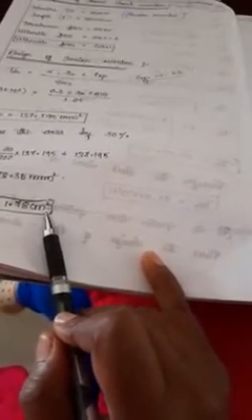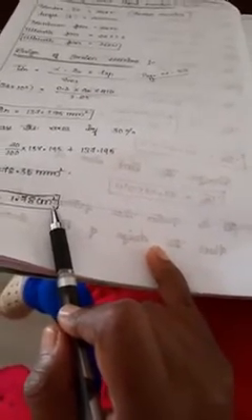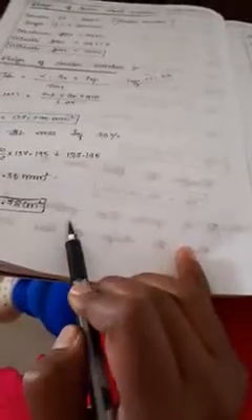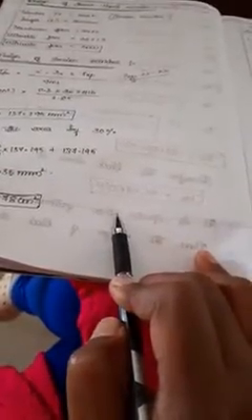For example 50 by 50 by 6, or 70 by 70 by 8, in that way you can select it. Don't select 70 by 75 by 6 like that. Both the sides of the angle, length and breadth, should be equal. Like this it is 50 and this way also it is 50. In that way you need to select your angle.